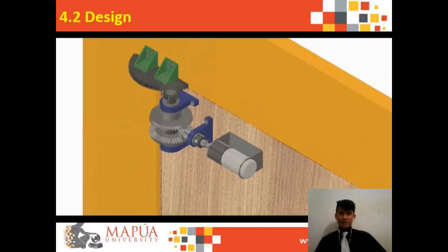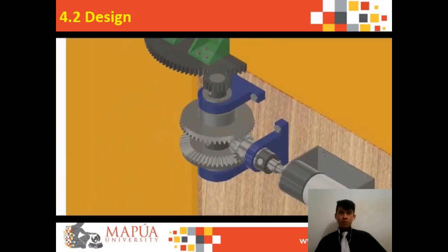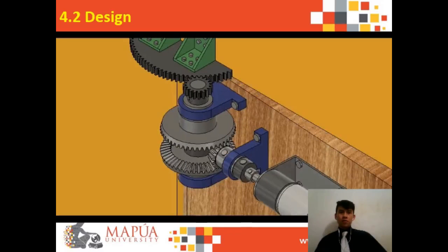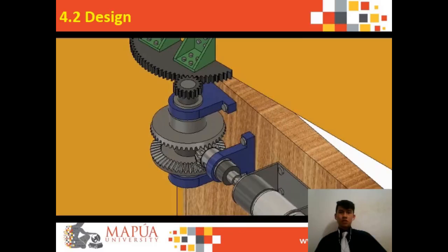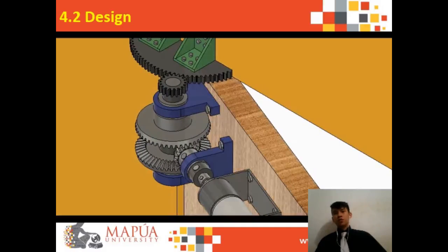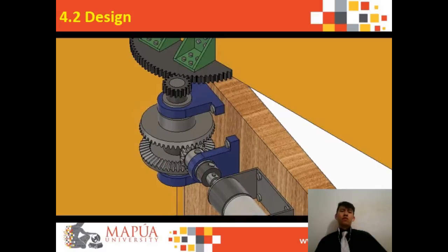And it's now playing. So the machine consists of a pair of spur gears where the pinion spur is compounded to the bevel gear, since the driving shaft changes direction of rotation when opening and closing the door. A rectifying mechanism using roller clutch bearings and bevel gears was used to rectify the rotation of the generator shaft.